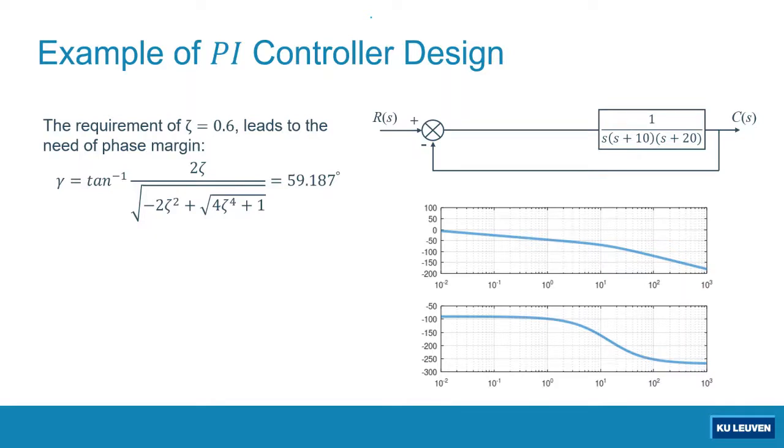You can refer to one of the formulas that I have already shared at the beginning of this session when we were discussing Bode plot analysis. I guess it was in the previous 3 or 4 videos. We can translate the information of damping ratio here to phase margin using this formula. Please take a look at your lecture note. I have already shared this formula with you.